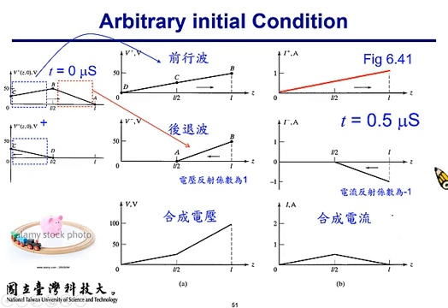And you can do the same to synthesize the I plus signal and I minus signal. However, the reflection coefficient of the open circuit for current is -1. The voltage reflection coefficient for open circuit is +1, and for the current it is -1.